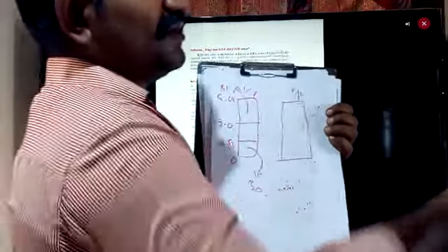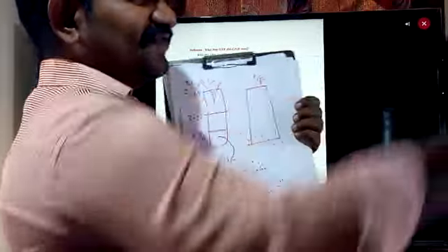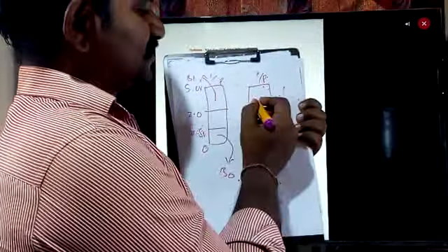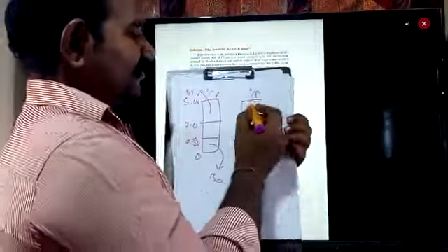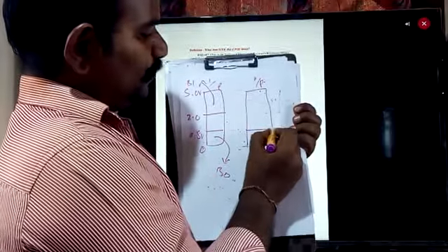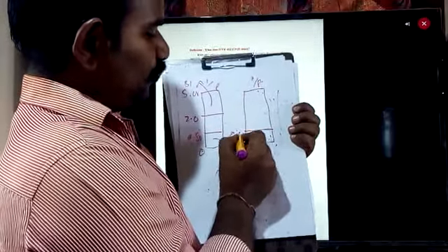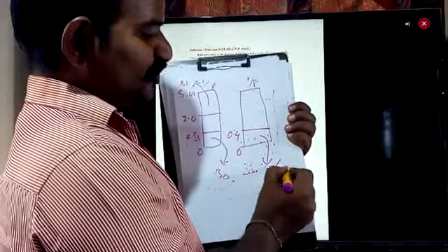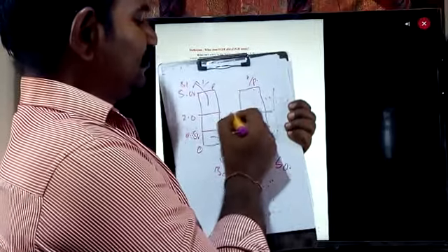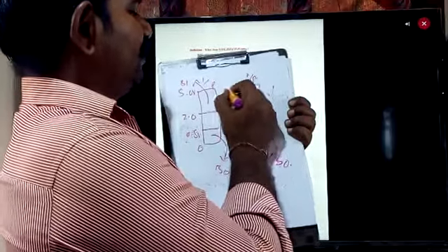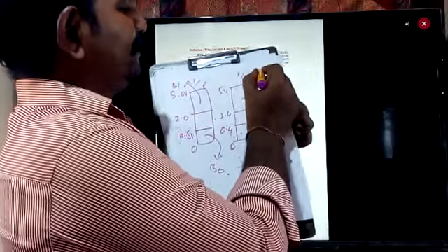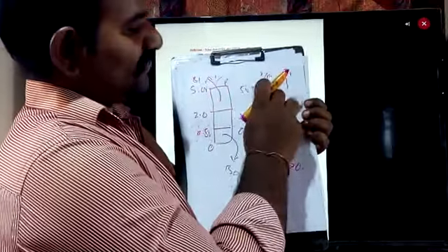When the same TTL family IC is trying to send the information, then at the output of that particular IC terminal, if the output is varying from 0 to 0.4 volts, it is going to be treated as a binary 0, and if the output is varying from 2.4 volts to 5 volts, it is going to be treated as a binary 1 in case of the output scenario.